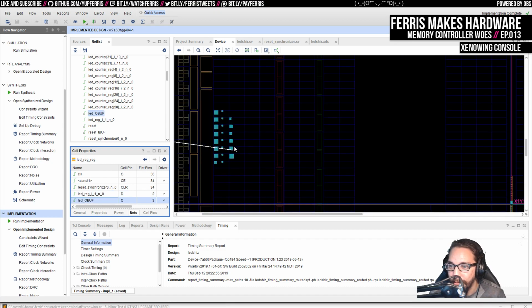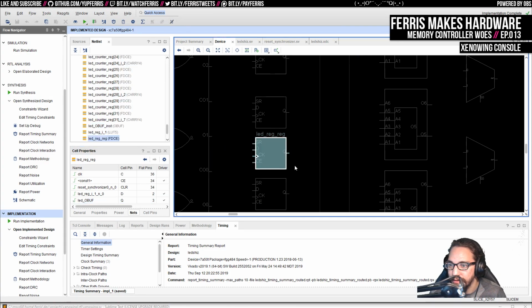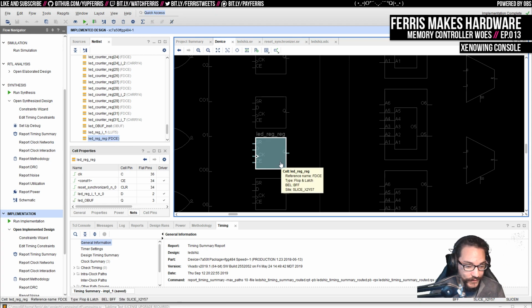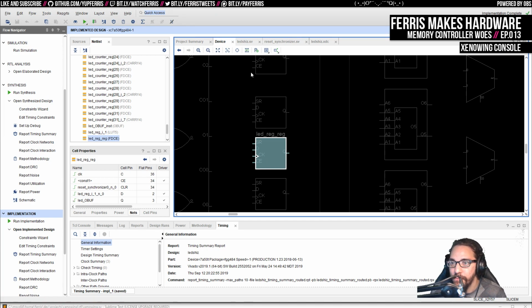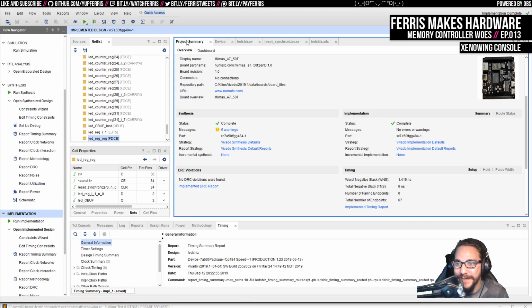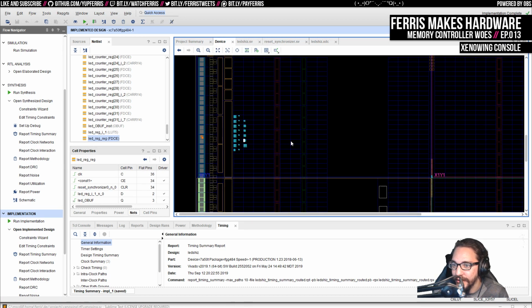Very cool. But yeah, when you're interfacing with external stuff that's actually timing critical, you need to check those slacks. Although again, if you have constraints set for those paths, it should report those if they're going to be problematic. So I guess the message of the day is: don't skip learning how to constrain your design. Because that's been a lesson I've definitely learned the hard way the last few weeks.